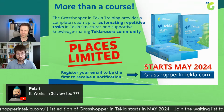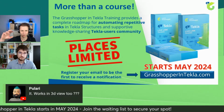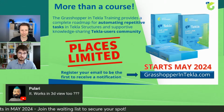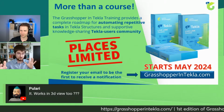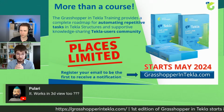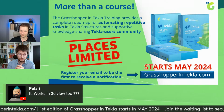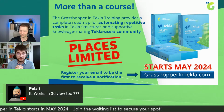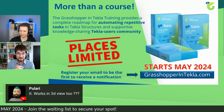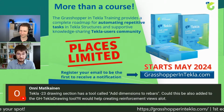Yeah. Have you tried to work with the 3D view? Let's say you have an object and you would like to export it as 3D, not 2D, to a Tekla drawing. You can definitely create the 3D view because it's just a matter of the direction of viewing, and then probably you can insert the dimensions, text, all of those other objects. But I have not tried it. Maybe, Polari, if you find some users, I'm quite curious how it can influence.